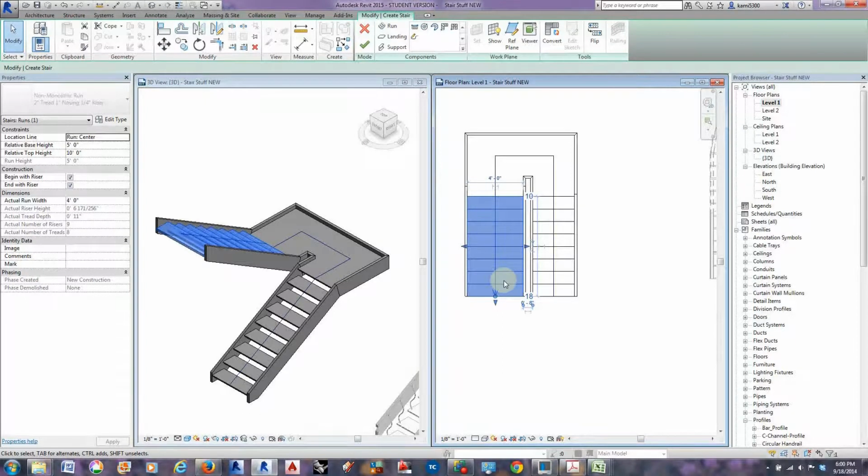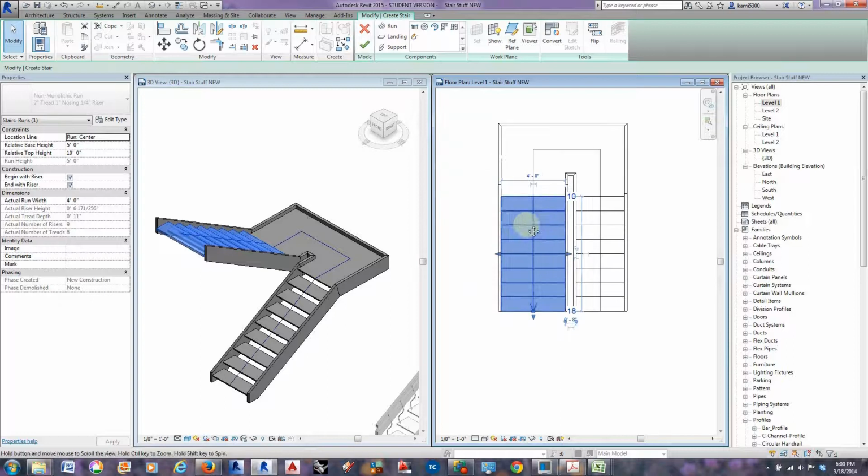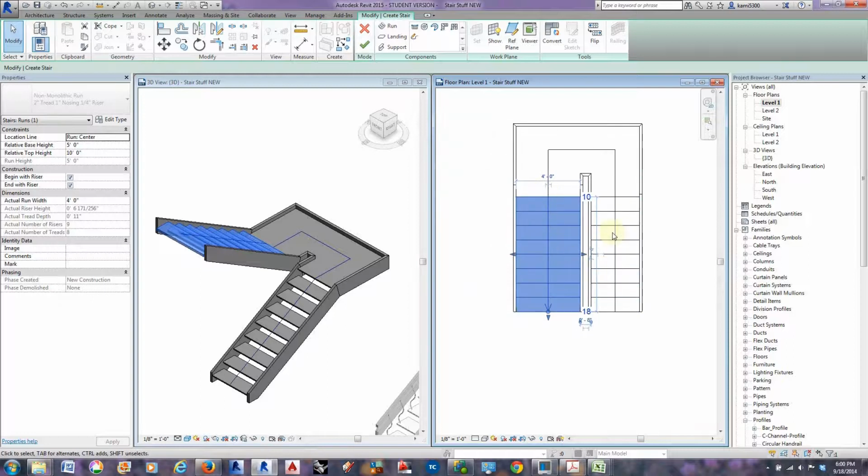So you can start to, in your projects, account for that, and you're not just saying, well, I just need a 3-foot stair, I'll be good. In actuality, you might have 100 occupants and you need 40 inches or 4 feet or 5 feet worth of stair as those people start to come down. And so you can change the width of your stairs for that particular reason.